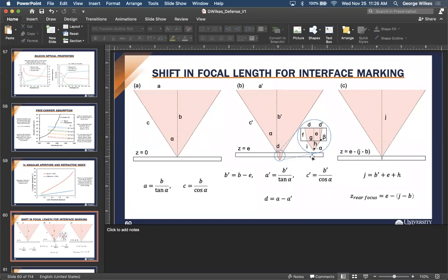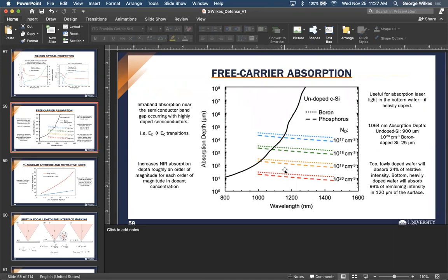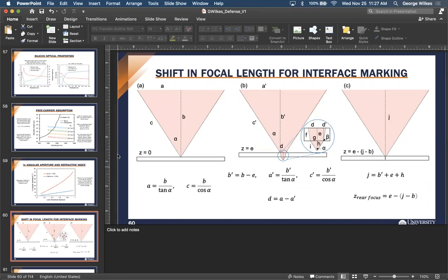I see. But if you focus it, the bonding interface will be localized, so it will not bond everywhere. Isn't that true? Right, it is. So it's basically just raster lines of bonding for this technique. I guess one idea is you have to keep it focused for this, unless, if you had a high enough doped wafer and a low enough doped front, maybe it could work. But I tried this without the high NA lens. I tried it with just a galvo lens, beta lens, and I wasn't having much luck getting the mark.